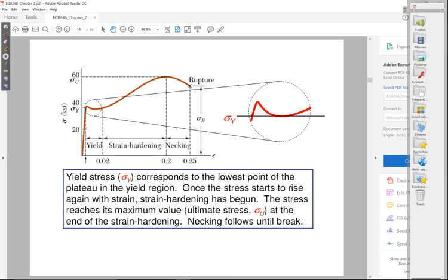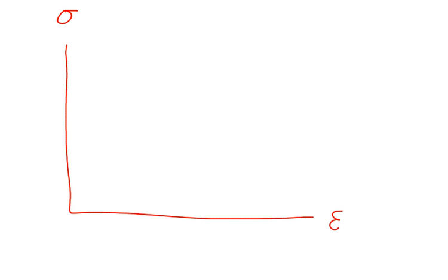So, let's go into detail here. Okay, that linear portion is usually referred to as the linear elastic region. It's linear, and it's elastic, meaning that at any point in this linear portion, if you let go of the force you're applying, your material just follows the slope, this line, back to the origin.